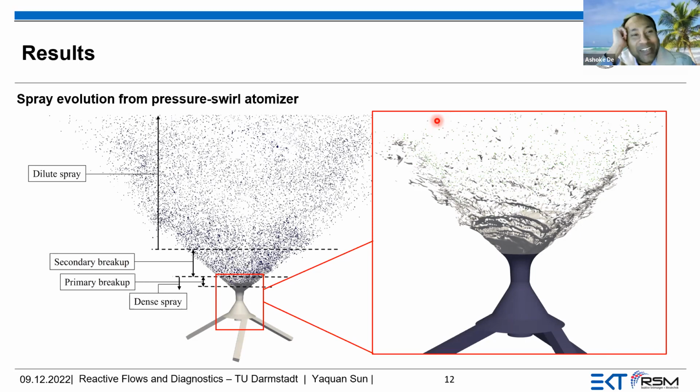Now I'm extending the thing a little bit further. When you have this superheated fluid or fuel, flash boiling occurs. How do we handle that? Because that allows some primary atomization close to the nozzle injector exit. In the Spray G2, we have a flash boiling effect, and there is also a model which accounts for this effect. So that correlation is there.